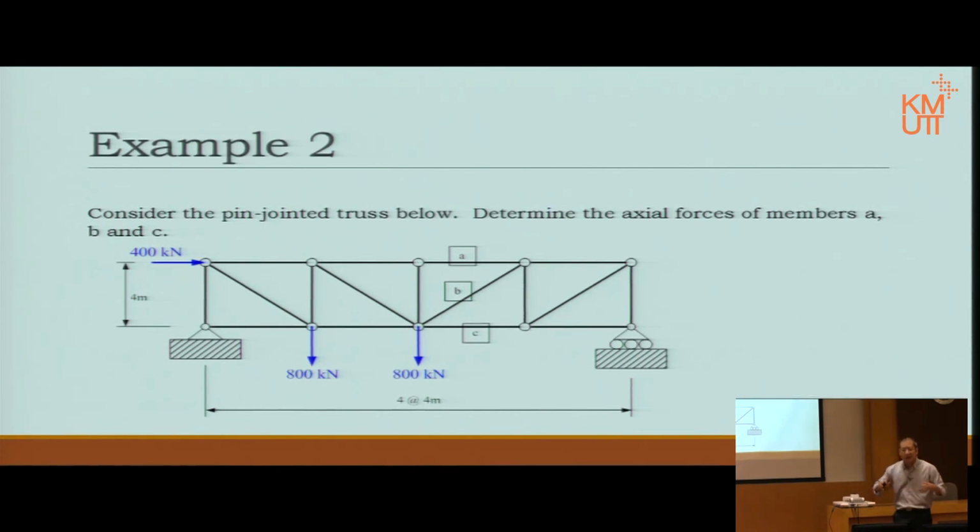Usually when we design the truss, we choose sections and calculate the maximum forces inside those sections and then design every member according to that calculation. Because it's the way we order steel. The more cross sections you have, the more member sizes you have, the more cut and throw away you do. Too much waste.